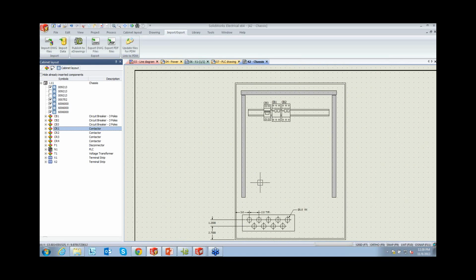As in, you always want some detail without having to worry about it, and I think for 2D, if you're not doing 3D control panel design, this is a really good tool. That's what I've heard from our customers, that it has a very good connection between your schematic and your 2D layout, so you know which devices to place. It's like your to-do list there, and you can hide the stuff that you have already placed, right? Yes, exactly. And you can also show other information like length, cut length, and how you're going to place some of your devices.